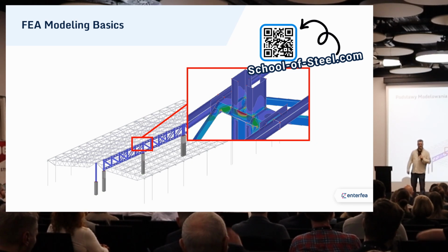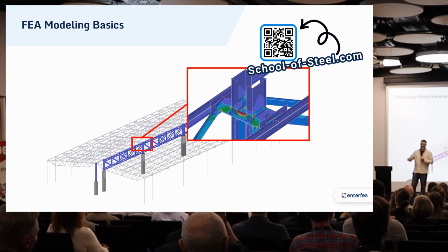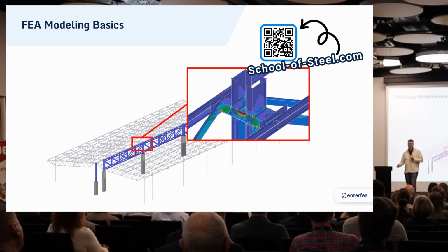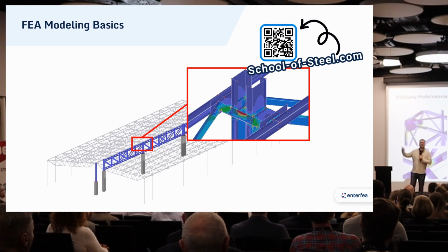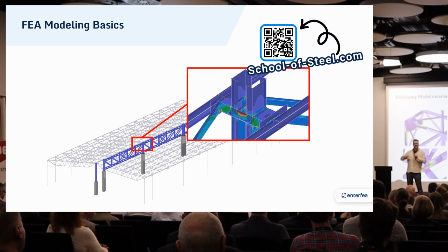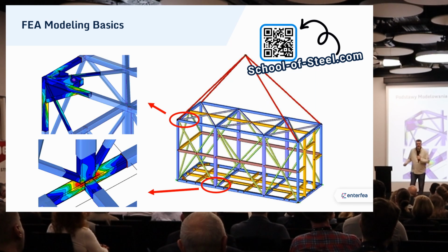Of course, the hope is that your node is in equilibrium, which means that in this one beam where you used the support, you hope that the reaction forces will be equal to the values of forces in your static model, and then you will be certain that you represented the situation of the node nicely. And as such, you can calculate such a cutaway model separately. This would work, but if you would have a lot of load combinations, it will be a huge hassle to transfer all the loads into your model.